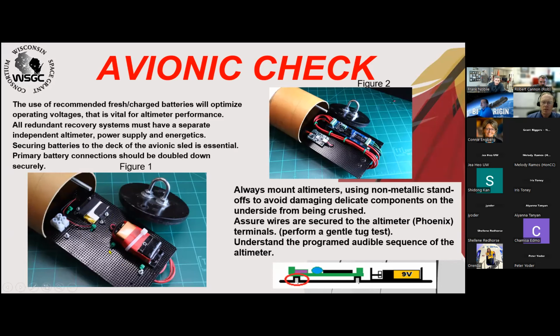This is just a straight flat 3D printed sled. And in figure 2, this is the back side of it with the avionics. I just have one avionics on this side and a smaller one on this side here, and you can tell all the wiring is strapped down and contained onto the sled, so nothing moves. All terminals are rechecked for tightening down and secured.